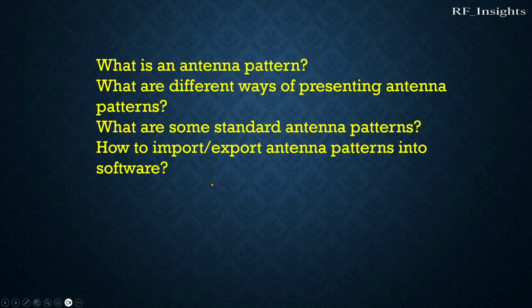So we are going through what an antenna pattern is, what the different ways of presenting antenna patterns are, what some standard antenna patterns are, and how to export antenna patterns into software.